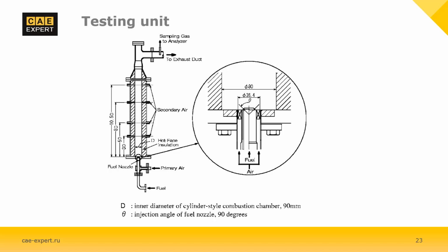In order to investigate the effect of the two-stage combustion on the fuel NOx and thermal NOx reduction, secondary air inlets at a distance from the fuel injection nozzle of 3 chamber diameters are used. The diameter of the secondary air inlets at the entry of the combustor is 13 mm, and altogether 12 inlets are positioned on the perimeter on one cross section.